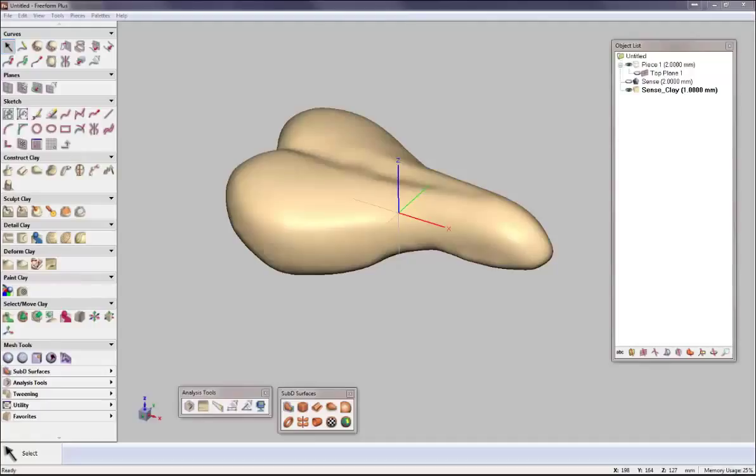Now things like the tug are a little bit different because it also grabs your perspective on the part. So you kind of have a 2D coordinate system of your screen, a point that you're clicking on the model. So it factors in the normal direction of the area of the model that you're working with, but it also will use the 2D directions of me dragging up and sideways to help give me a direction.